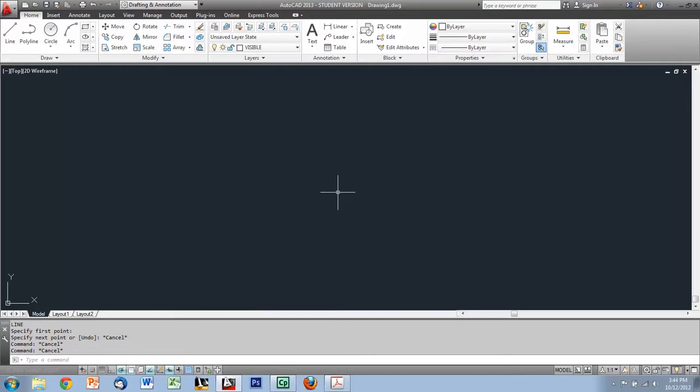That way if I have to draw a line at a 15 or 30 or 45 degree angle, I can guarantee that I'll be able to snap to that angle while I'm drawing. So 15 is a pretty good all-around setting. That's what I'd recommend you set your polar tracking on for your template.